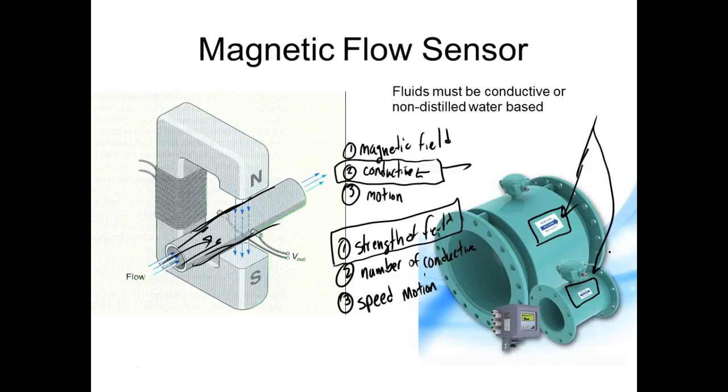What determines the size of the pipe? How much flow you get. So the inside diameter determines how much flow you're trying to get, right? It's just like a conductor. The bigger the conductor is, the less resistance the conductor has, for the same material. Well, that's the same thing through here. But you're not going to use a big old thing like that to conduct 5 gallons per minute, right? You understand? Because as the size of the conductor goes up, what goes up? The cost of it goes up.